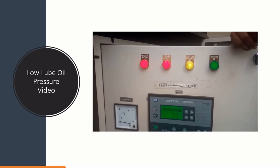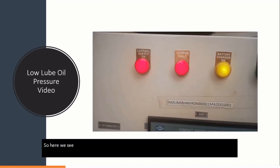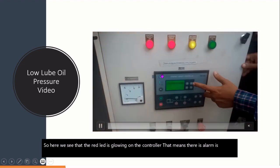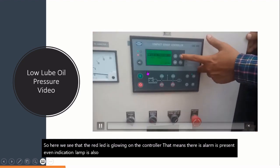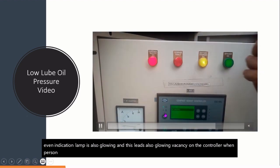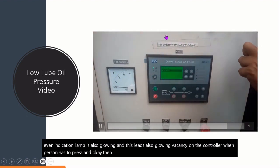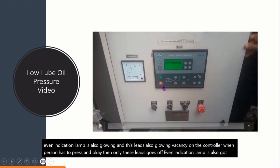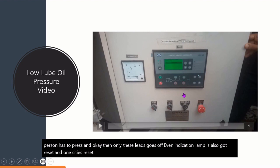So here we see that the red LED is glowing on the controller, which means an alarm is present. Even the indication lamp is glowing, and this LED is also glowing on the controller. When the person presses OK, only then this LED goes off. The indication lamp also gets reset, and once it is reset, only then can we start the engine in manual mode from here.